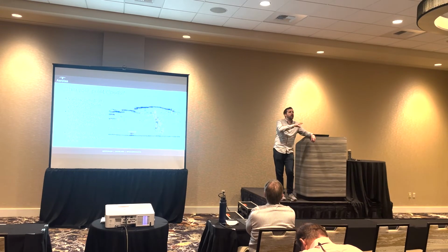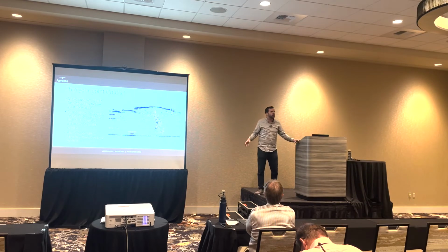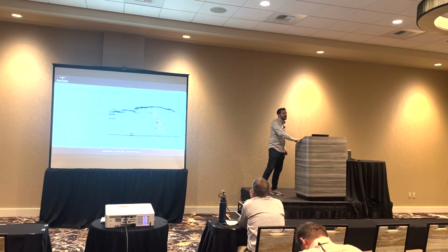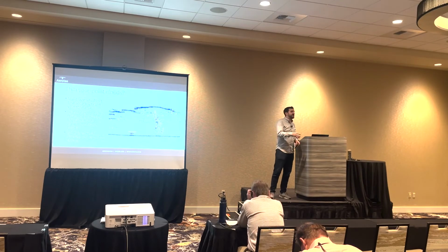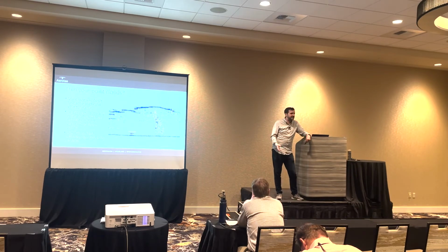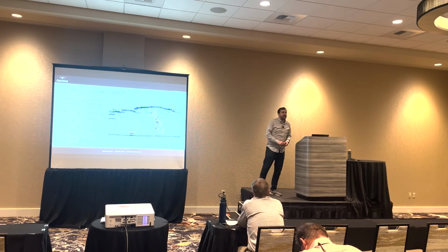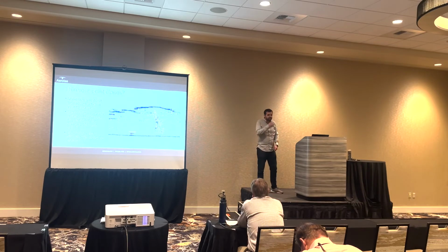So any sort of automatic break line detection tool is going to work way different on an aerial LiDAR versus a terrestrial LiDAR system. I say that because I process primarily aerial LiDAR data, and I know just enough to be dangerous about terrestrial LiDAR data, and enough to know that these workflows are different. Some of the principles can probably be applied to ground-based LiDAR, but the exact software and routines probably shouldn't.